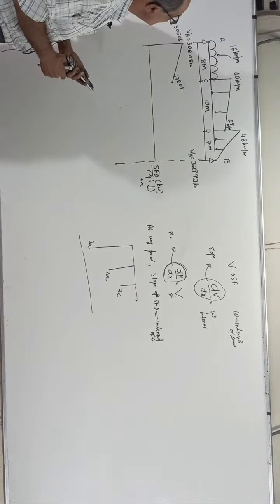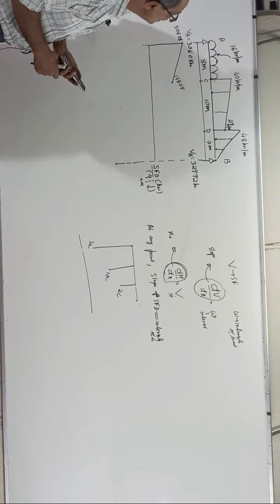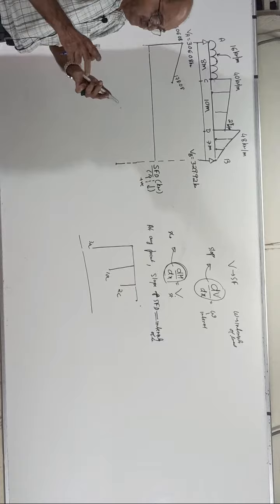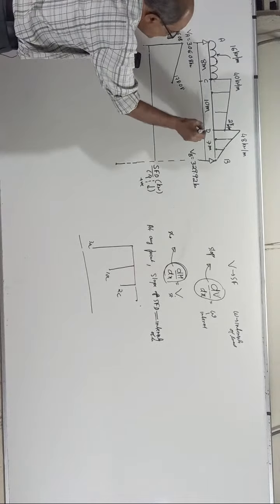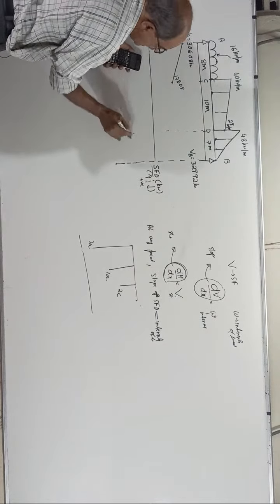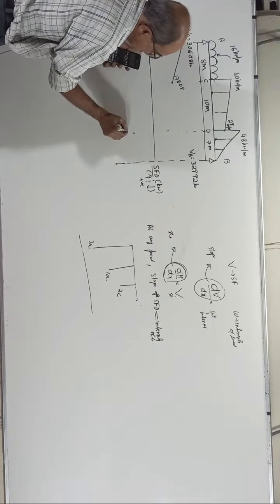That is 28 plus 40, half is how much? 34. It is 340 kilonewton. So if you come down by that much, this ordinate here will be 161.92. 178 here, 161 here. Reasonably okay.